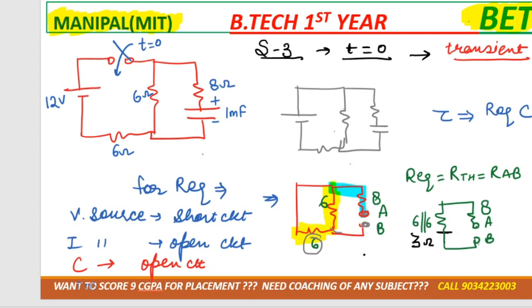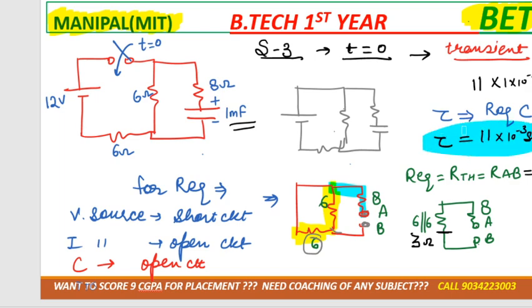Both of them are in series. So 6 parallel 6 is 3. 8 plus 3 is 11. So from this we'll get the value of R equivalent is 11 ohm. Okay, and the capacitor value they have already given, that is 1 millifarad, 1 into 10 raised to power minus 3. So ultimately we get it as 11 into 10 raised to power minus 3 seconds. This is the value of the time constant, we got it, and this is what we need to calculate.